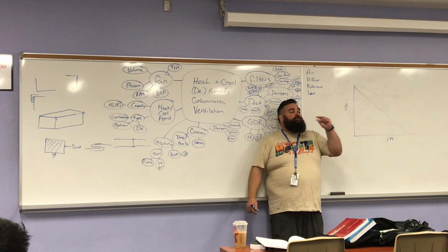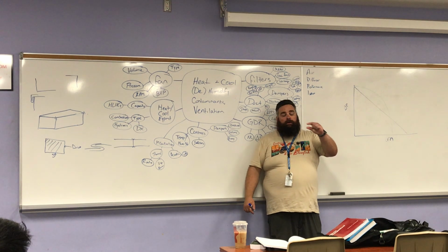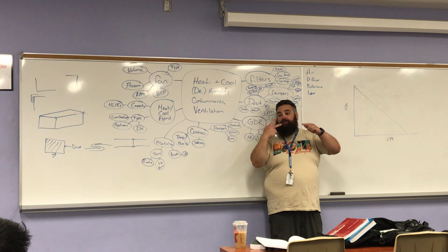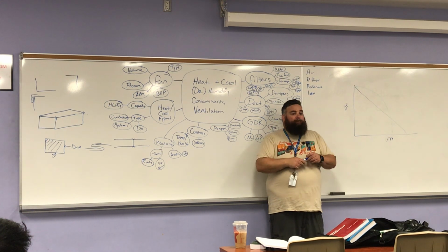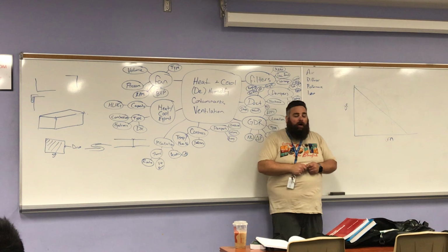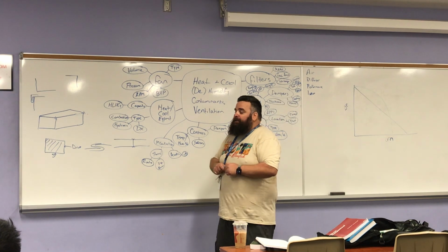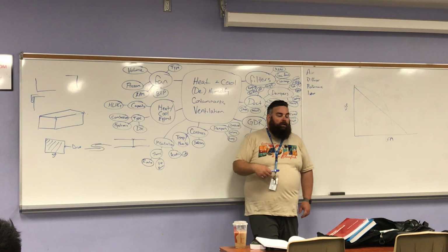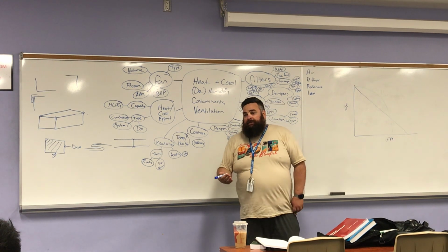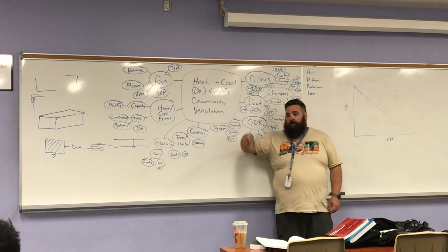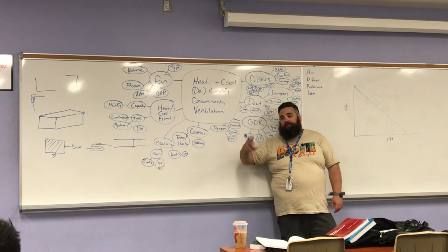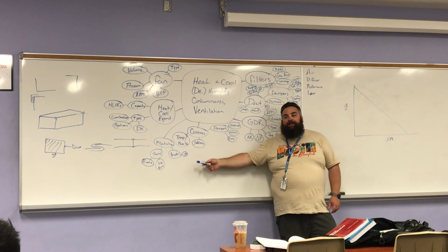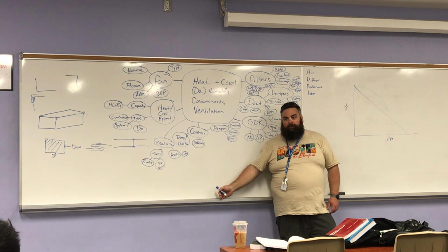If I have 1 inch acoustic insulation, now I've really decreased my duct size by 2 inches on each dimension, haven't I? So I have less free area. So what you'll often see on plans is that the contractor is to increase the duct size accordingly. What that tends to mean is if you put 1 inch insulation on each side, I want you to increase the duct dimensions by 2 inches on each side. That will address your free area. It doesn't address your roughness, okay?